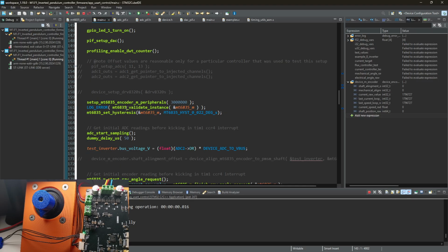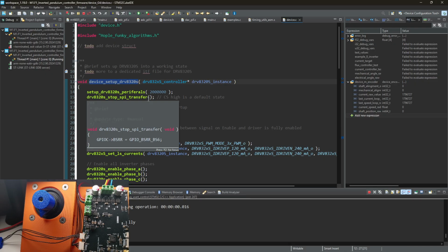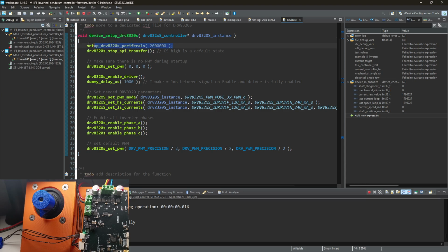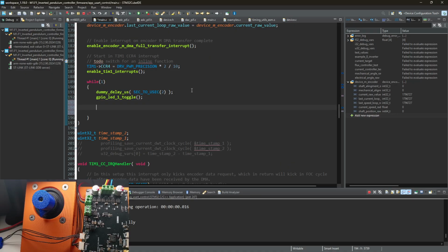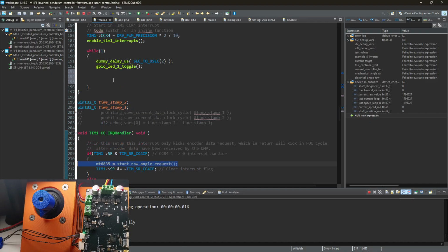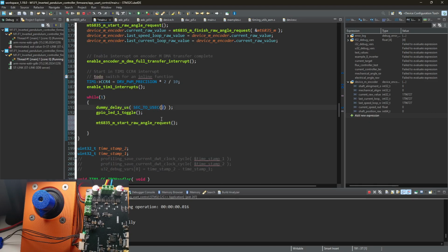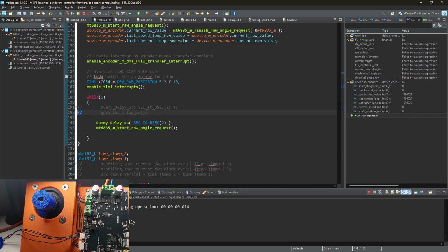Okay, so we do need this function, or actually part of this function. And the part is that we need to set up peripherals. But if we do set up peripherals, we actually already set up everything else. Instead of setting peripherals there, let's actually add the measurement code here. So let's do it like this. Just put in a better delay. Remove this line, remove that line. Change this delay from seconds to microseconds, to 90-ish.